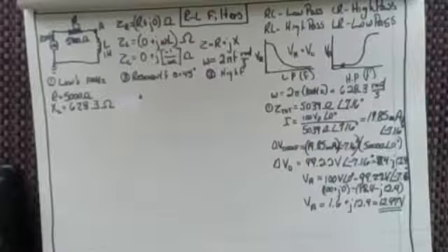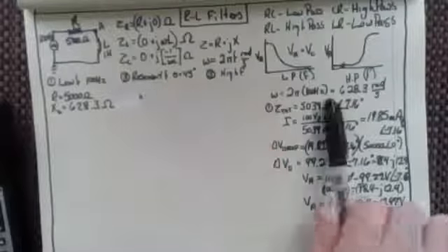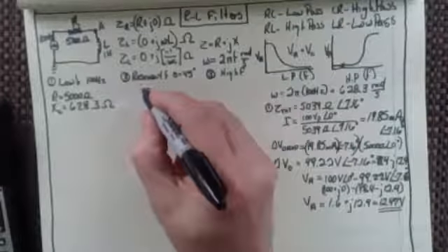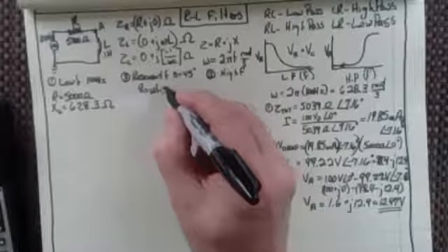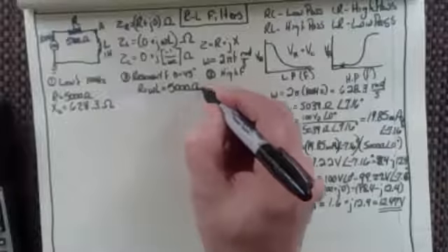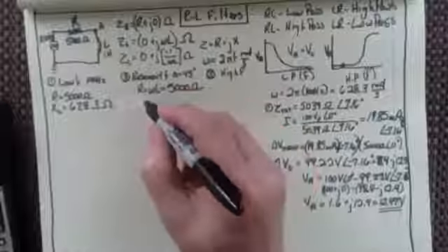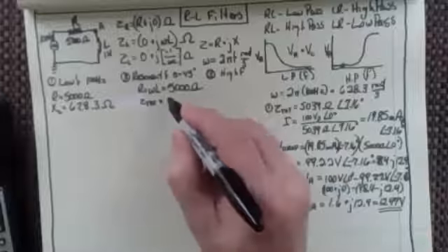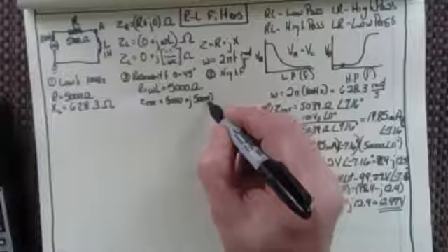All right, well, let's change the frequency now so that both of these are equivalent to one another. And before I do that, let's just look at if I were to make them equivalent to each other. Let's say that at resonance, R equals omega L equals 5,000 ohms, right? So if they both equal 5,000 ohms, then if I looked at the total impedance in that series circuit, it would be 5,000 ohms plus J 5,000 ohms, right?